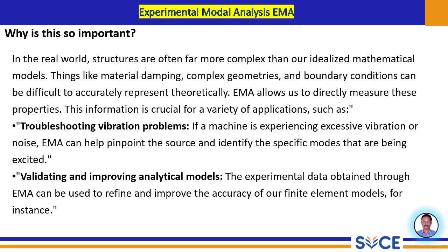As we are discussing, the complexity of real-world structures makes experimental modal analysis incredibly valuable. When we are creating mathematical models, we often have to make some assumptions. We might assume uniform material properties, perfectly rigid connections, or idealized boundary conditions.